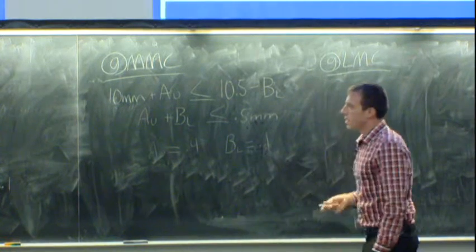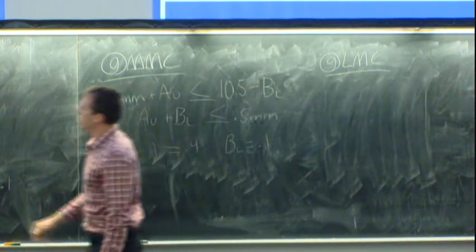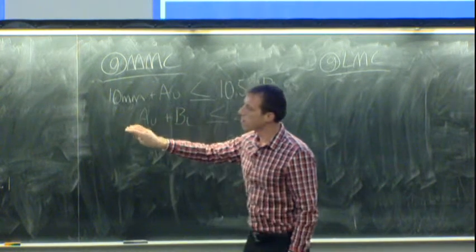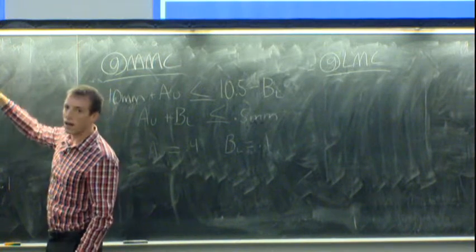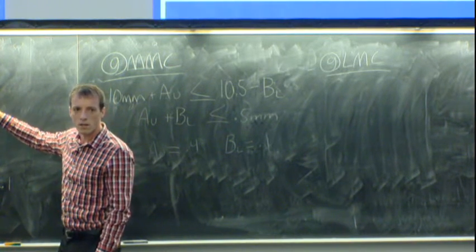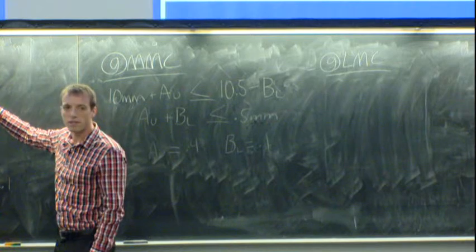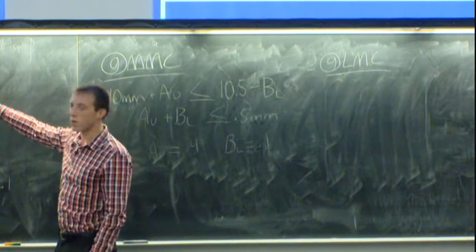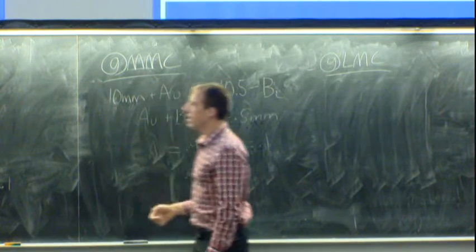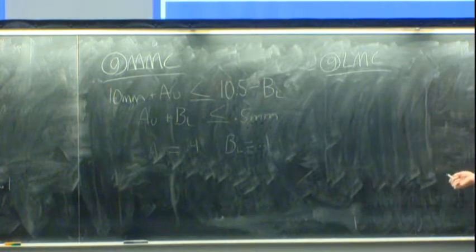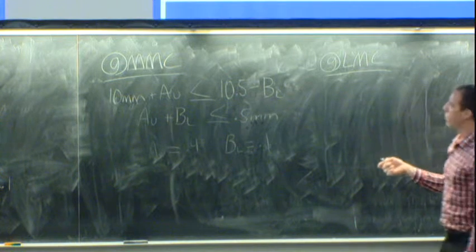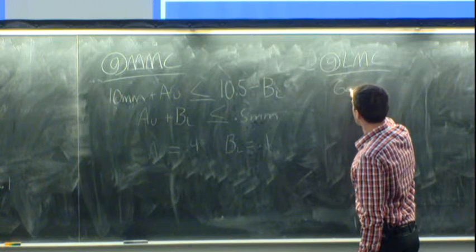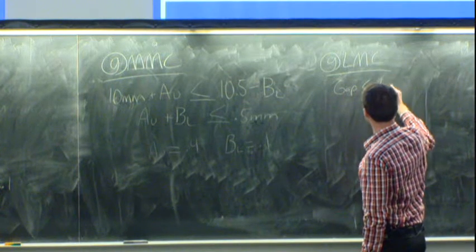But what you're really interested in is how loose you'll allow the shaft to be in the hole. You could do some geometry and say I'll allow it to go to 10 degrees or some angle. What your bound is is kind of arbitrary depending on your application. It may be that you just want it in there. You don't care how loose it is. We'll say, for the sake of doing the calculation, that you'll allow a millimeter. So you're saying my total gap should be less than or equal to a millimeter.